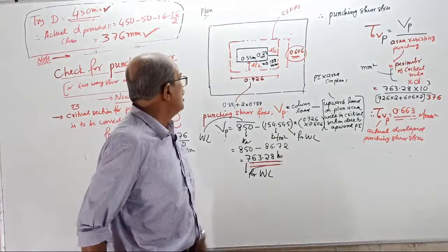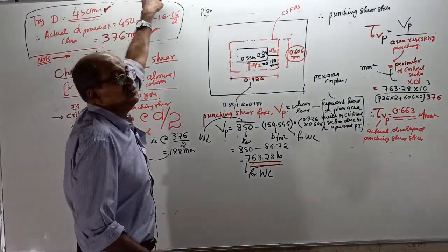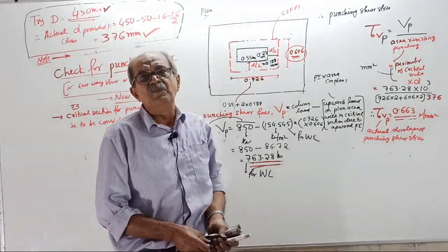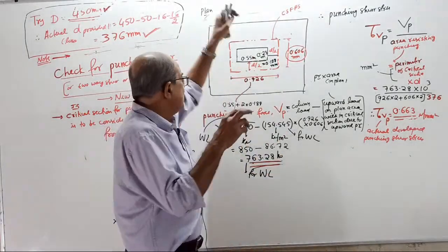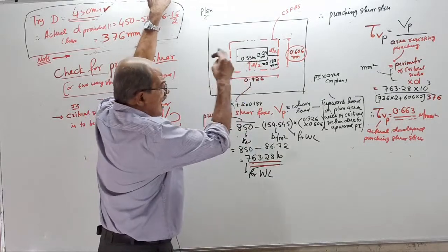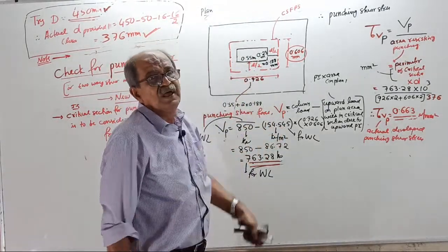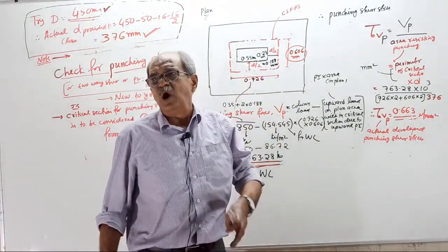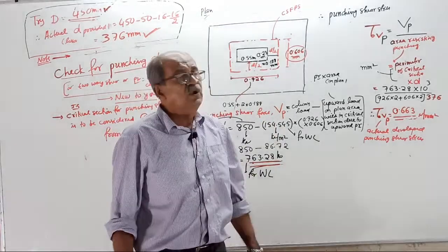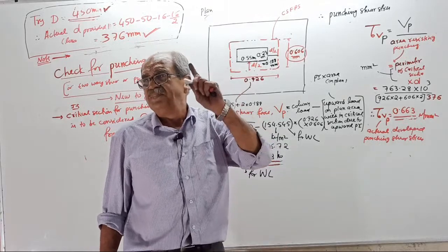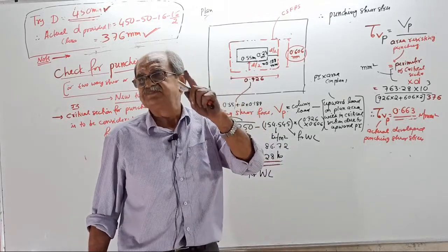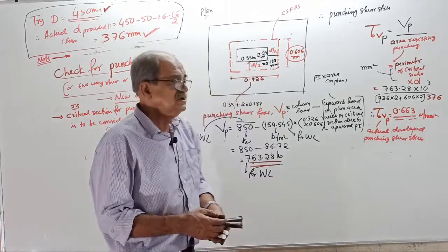After telling so much just earlier, someone will tell, sir, that is for bending moment. Go and see the recording. I told, since you are using the working column load and the pressure due to working load, anything you get is for working load. Therefore, in the limit state method, any calculation you make, you should without forgetting get the corresponding factored values.